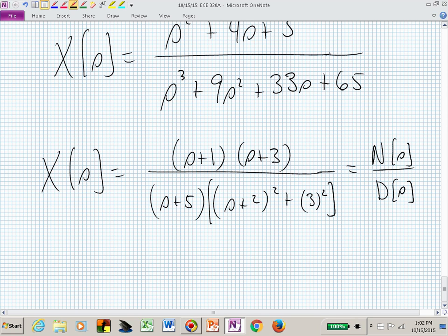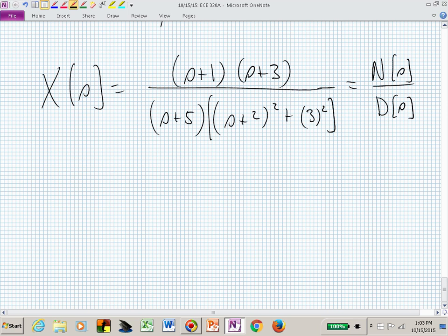In general, you could say, okay, I have e to the minus 5t with some weighting plus some other weighting e to the minus 2t cosine of 3t plus another weighting e to the minus 2t sine of 3t, and you're done. That's the structure of your answer. And you know that just by factoring the denominator. What we want to do now, though, is introduce more formally what I've been mentioning already, and that is this concept of poles and zeros.